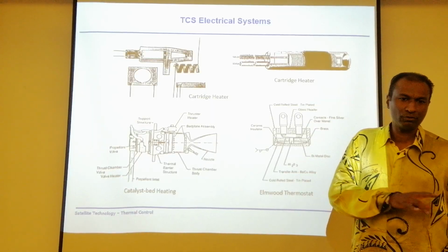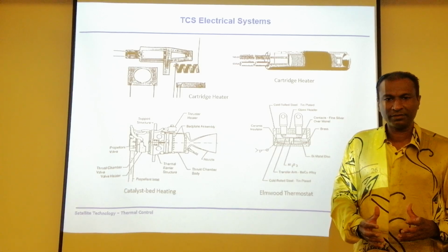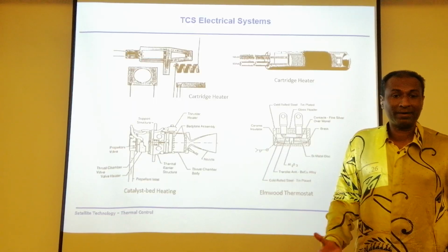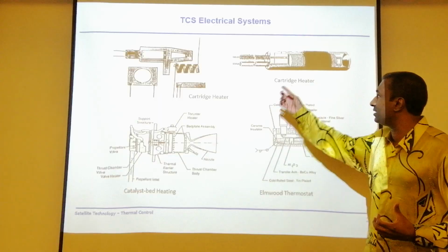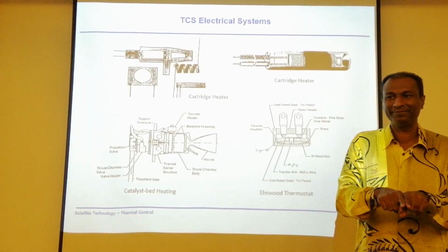It will be cold when you even go into the eclipse part. So for those kinds of areas, you need to maintain, let's say, 10 degrees. It drops down maybe to -5, -10. Then you have these cartridge heaters to do heating instead of cooling.